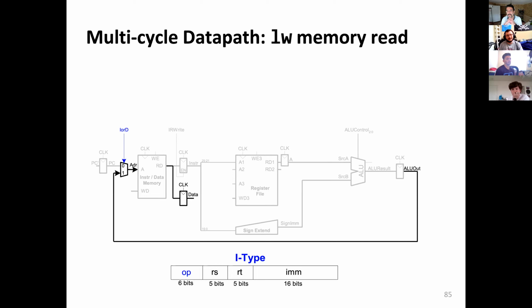I think I've got it now. We added that flip-flop, which is contrary to us trying to eliminate everything, because now that we're in multi-cycle architecture, we need some way of telling the hardware that we're not too busy with one operation. So that flip-flop is in there to store that data until we're ready to use it again. We run through the first part with the instruction, and after that leaves the ALU, we increment the program counter during the second part while the other operation is going on. So that flip-flop is there just to provide a bit of lag behind so that it works out.